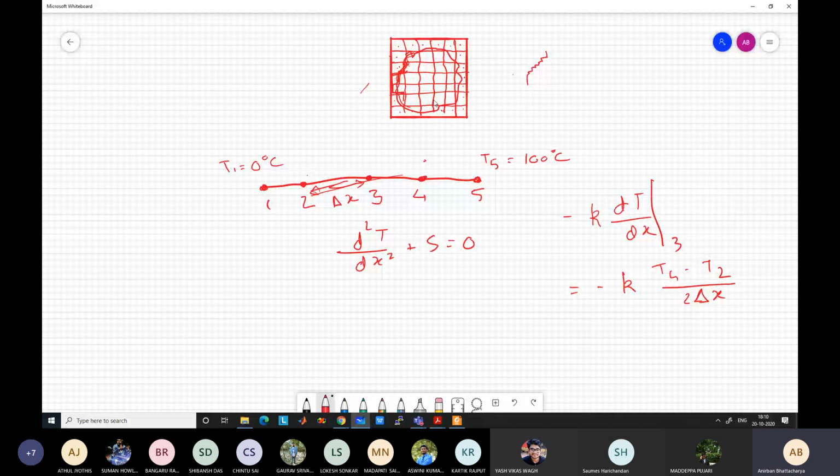But what is the main drawback of this? The calculations at the interface are not very accurate. There are a lot of interfacial properties, for example shear stress at the interface or heat flux at the interface. This type of calculation will not be accurate because you are not accurately capturing the interface. Your interface is like a staircase in this case.